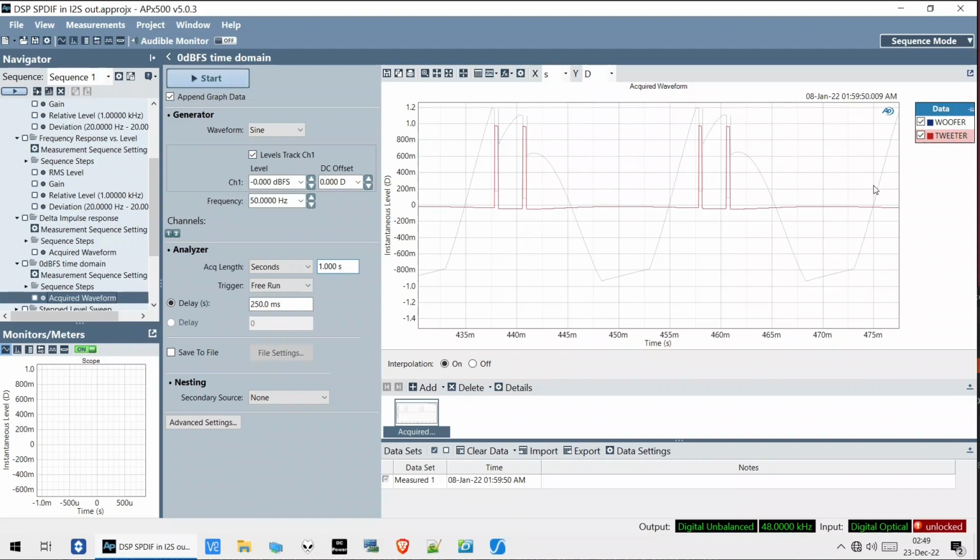redesign the DSP. And then the next question is, of course, are we going to try to recreate the original coefficients? Can we somehow get them out of the flash, or can we recreate them from the AES papers and the measurements in this file? Or do we just design a parametric EQ and redo the tuning from the beginning and go from there? That, I think, is something I'm gonna leave to the next installation.